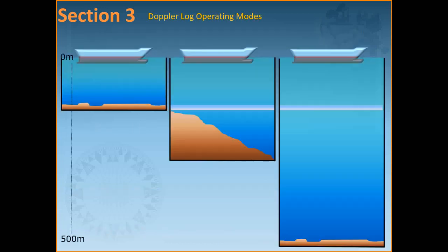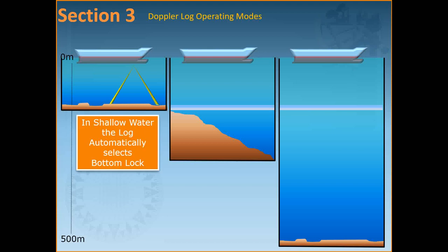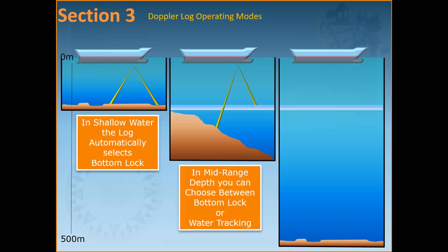If speed measured in bottom track differs from the speed measured in water track during that time, then definitely there is a current that exists. A log may be able to hold a bottom log down to about 200 meters. It might use a water reference layer at about 20 meters or 30 meters for water track. This log may operate at minimum underkeel depth of about 2 meters.